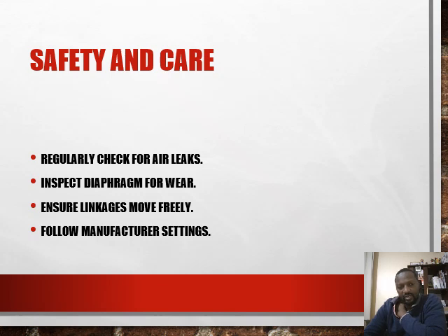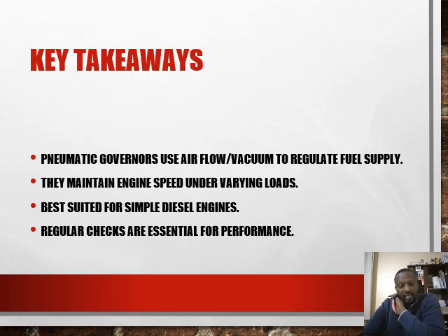To maintain it, it is good that we check the unit regularly for air leaks. The diaphragm should be inspected regularly, and we ensure that the linkages move freely. And of course, any adjustment should be made according to the manufacturer.